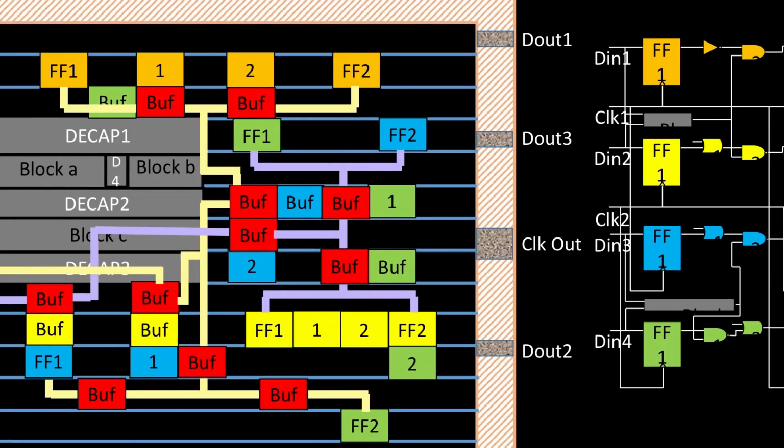And plus clock. The clock network needs to be built in. Ideally we want zero skew, but zero skew is close to impossible, so we go for a minimal skew between two clocks. I hope everyone knows skew. It's basically the time difference it takes for the clock signal to reach either of the flip-flops, from flip-flop 1 to flip-flop 2. The difference between those times is called the skew.